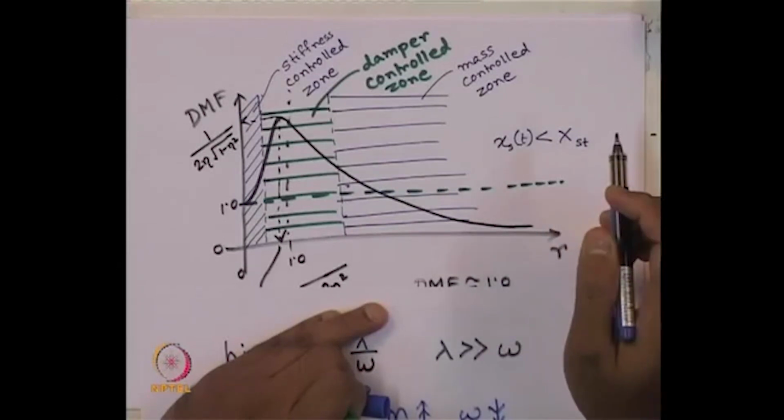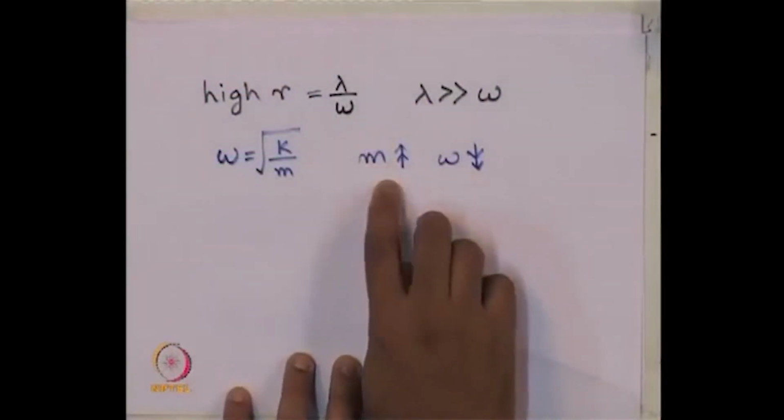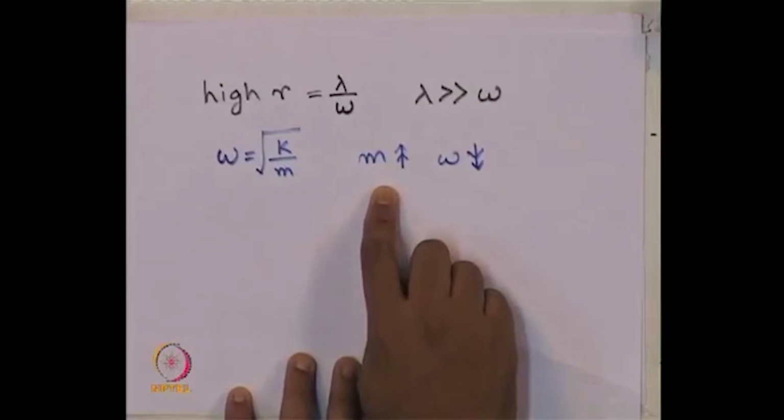So, for that kind of foundation, if we have designed it properly to take care of static load, that is good enough for taking care of the dynamic load. So, we need not design it specially for the dynamic load. That is one added advantage we are getting: without having a proper knowledge of dynamics, even if we design it very well under any static load, it should be sufficient to take care of the dynamic load, because of this reason of very high value of mass.